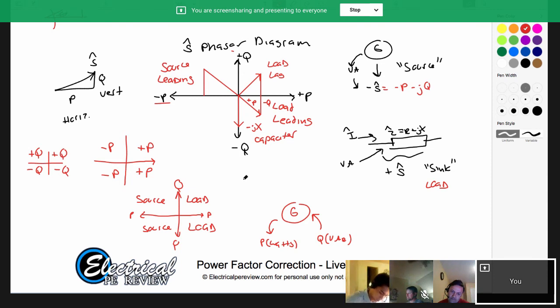Here's a great qualitative question. You can use an induction machine as an induction generator, but the reason why they don't do it very often is it's actually going to require VARs to operate. It's going to consume reactive power in order to operate.